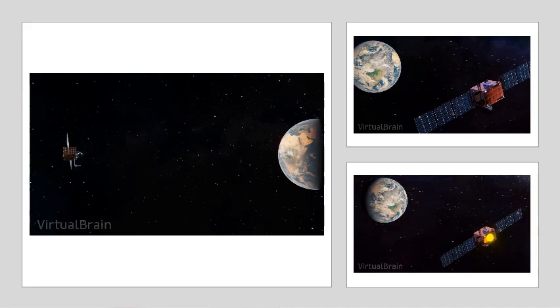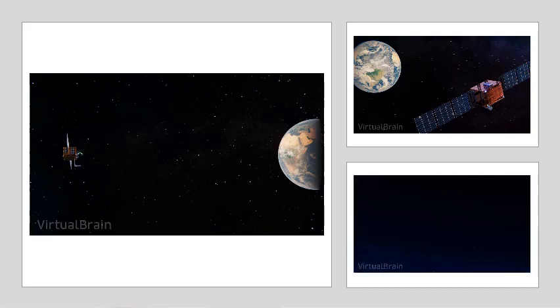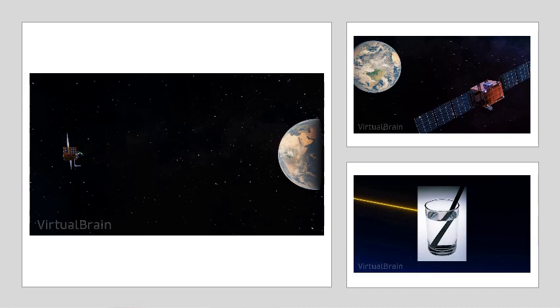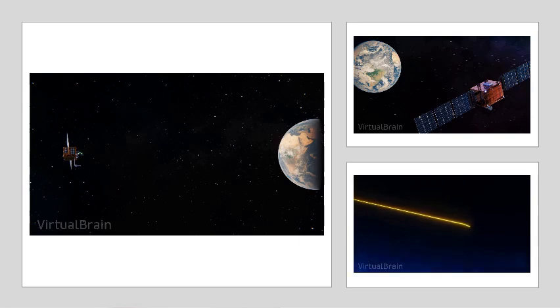Now the third one is the atmospheric layer. Due to the effect of the atmospheric layer, it is just like when we see through glass or water, which distorts. There is variation due to the change in refractive index of the propagation medium, because of which the signal experiences slight deviation in its trajectory and in its propagation speed as well. From the video you can see that when it travels through different atmospheric layers, it has a slight deviation and a change in speed.